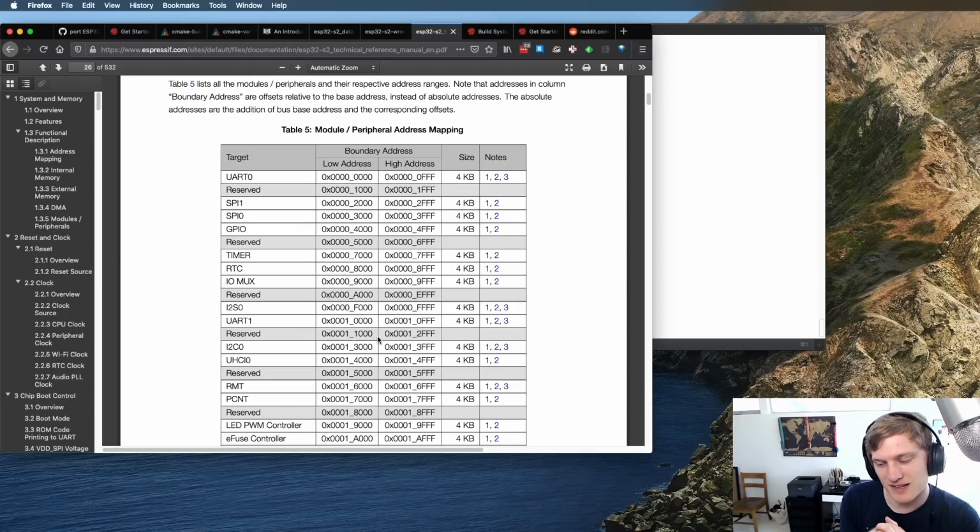The top of the line of the IMX RT does have onboard flash. I would be interested to see how fast the onboard flash is, because I bet it's still pretty slow. But they have caches there as well. My theory is that the way MicroPython and CircuitPython work is that there's this big loop, right? And this big loop is, depending on the Python bytecode you're running, run a chunk of C code. And I think that means that as your Python code is running, it's churning through a lot of different C code. And so if you can manage to get that C code squirreled away close to the CPU, because you know you're going to be doing that loop, then you can free up any sort of caching resources that you have for all the dynamic stuff that you're loading, like the bytecode or the C code for the individual modules that you've loaded in.